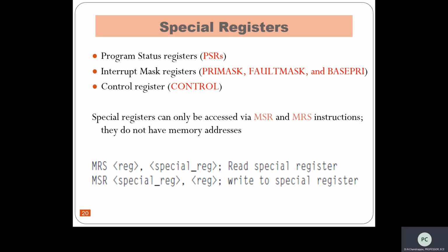The previous one reads the content from the special register into the register, and that belongs to the instruction MRS. The second one is MSR, which moves the content from the register to the special register.